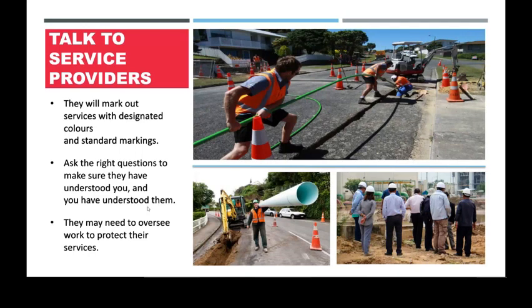In some cases, if you're close to it, like a high voltage cable or something, you may have to get a permit to work in that vicinity. And in some other cases, they may even have their person on site standing over watching what you're doing to make sure you don't damage their network. So it can get pretty technical. That's more likely to be stuff in the road, like what these guys are doing, water main repairs or stormwater or sewer repairs or replacements.